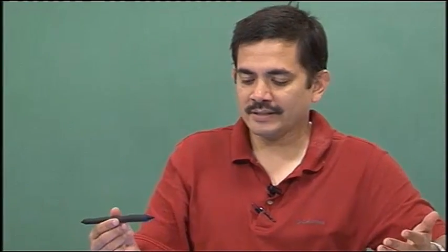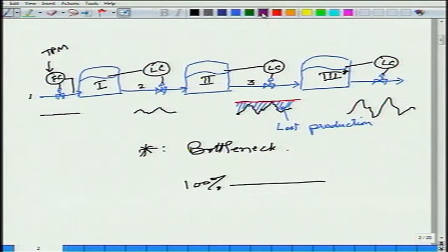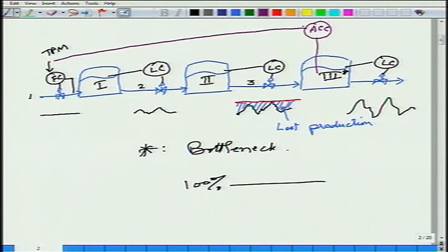I can automate this by saying that, look, I am looking at my constraint variable, I will call it an active constraint controller. Okay. The job that the operator is doing, a controller can also do. So it is setting the throughput.